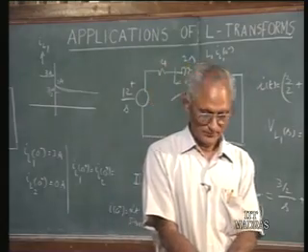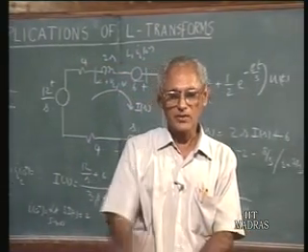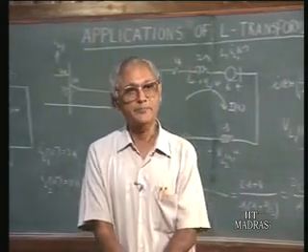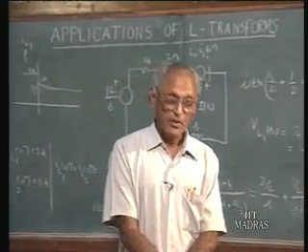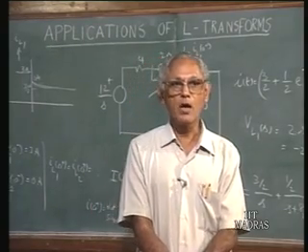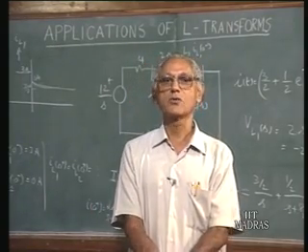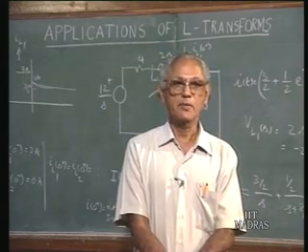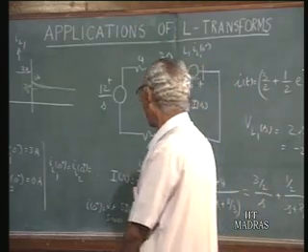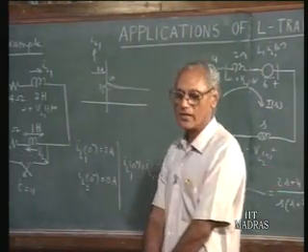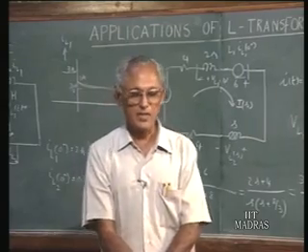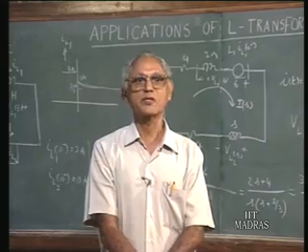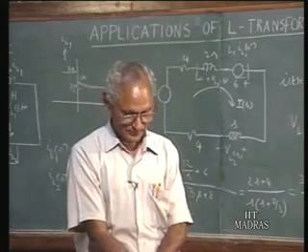That becomes quite complicated, whereas in the transform domain, for the entire range of time, you have one single simple expression in the Laplace transform domain. Secondly, we observe that we do not have to involve ourselves with calculus operations, no integration, no differentiation. All the equations describing the behavior of the system are put in purely algebraic form. So, calculus is converted into a kind of algebra, because differentiation corresponds to multiplication by S, integration corresponds to division by S.